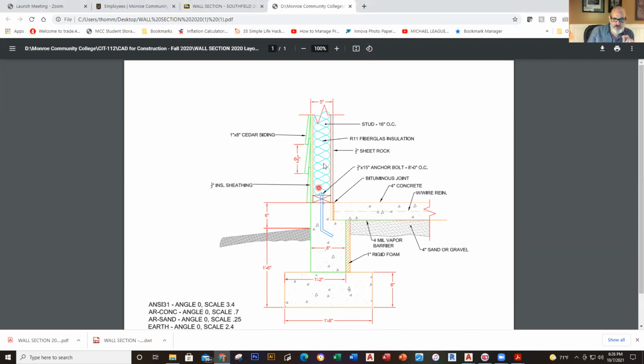Okay, first of all, this is your wall. You've got the wall right here, and you're only seeing part of it. There's insulation in the wall, and this is a 5-inch wide wall. But you see 5 inches right here. Now we file this down, and it's got an anchor bolt. It's actually got a 2x4 that's holding it down right here. So you've got the anchor bolt right here, and then this is your concrete floor in your basement.